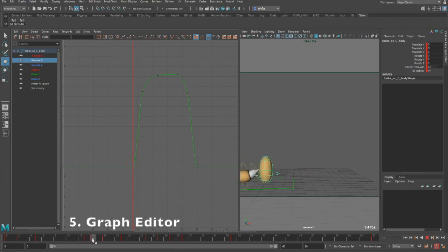And we want to give more of a sense of a drastic change to this key. So instead of selecting the key and rotating everything up to make more of a linear effect, more drastic change, we can go here, select the key, and go to break tangent.